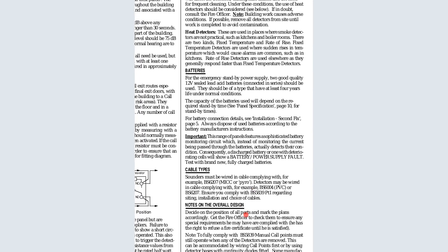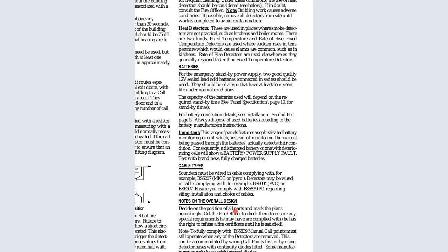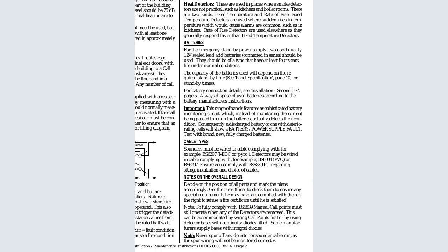This range of panels features a sophisticated battery monitoring circuit, which instead of monitoring the current being passed through the batteries, actually detects their condition. Consequently, a discharged battery or one with deteriorating cells will show a battery power supply fault. The test will run on a new, fully charged battery.